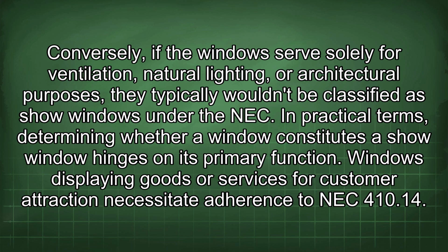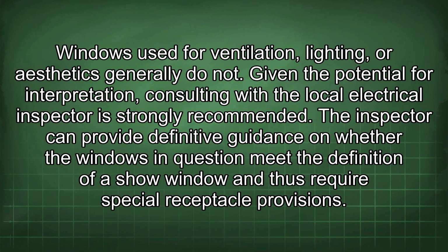Conversely, if the windows serve solely for ventilation, natural lighting, or architectural purposes, they typically wouldn't be classified as show windows under the NEC. In practical terms, determining whether a window constitutes a show window hinges on its primary function. Windows displaying goods or services for customer attraction necessitate adherence to NEC 410.14. Windows used for ventilation, lighting, or aesthetics generally do not.